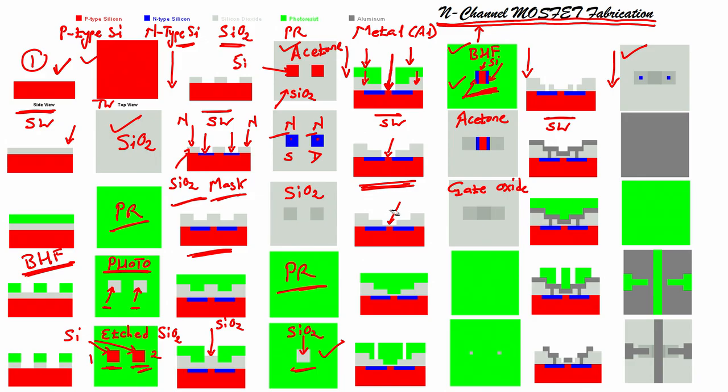So, what we have done? We have grown a thin layer of oxide into this window, that is over the source and drain, such that it overlaps the region of source and drain. So, what we have done? We have grown a thin layer of oxide, which is our gate oxide. Okay. Until here, is this clear? Yes, okay. No, then you read once again. Okay. So, if you are with me, we have here our gate oxide.